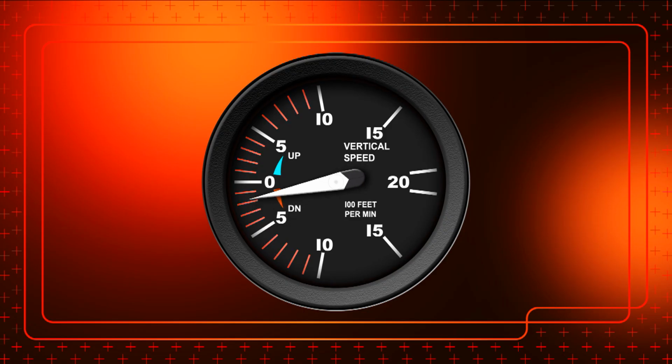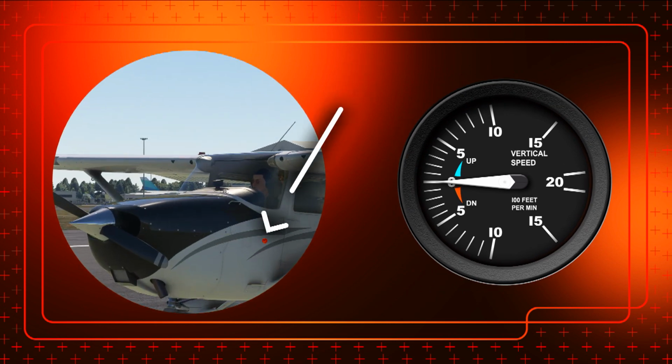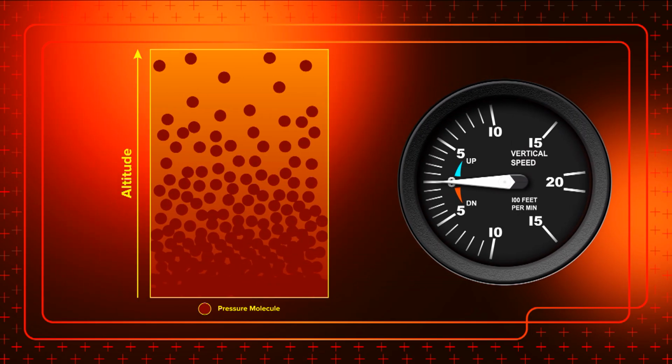Moving on now to how the instrument works, the vertical speed indicator gets its information from the aircraft's static port, which is situated on the outside of the aircraft. You may ask, how does the instrument take static pressure and then convert that into either a climb or descent rate reading? Well, the instrument takes differences in static pressure, which is also known as atmospheric pressure, when the aircraft climbs or descends, and then converts that into a reading for the pilot.